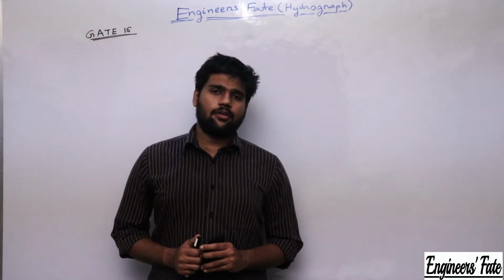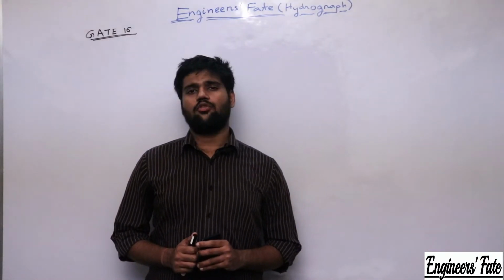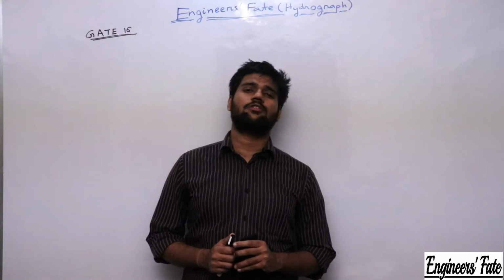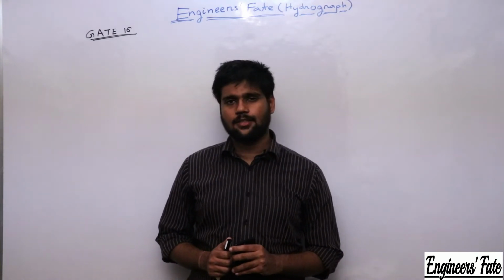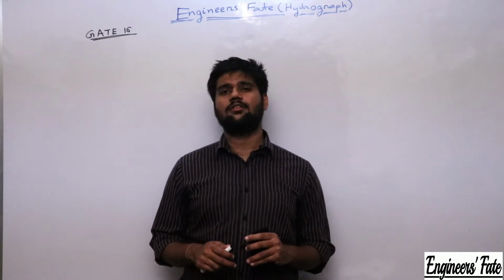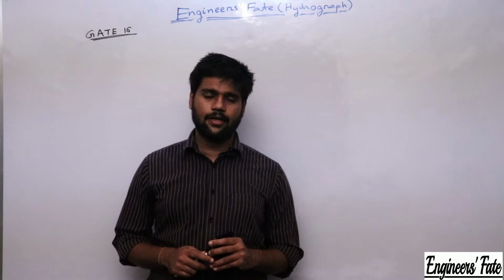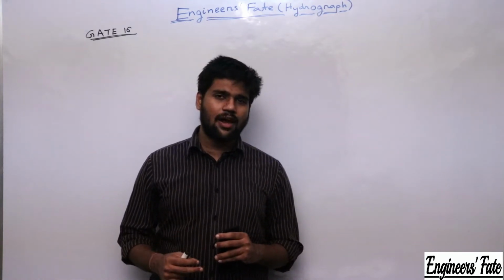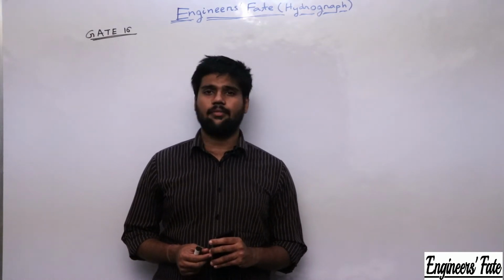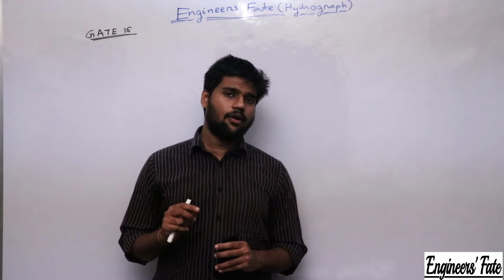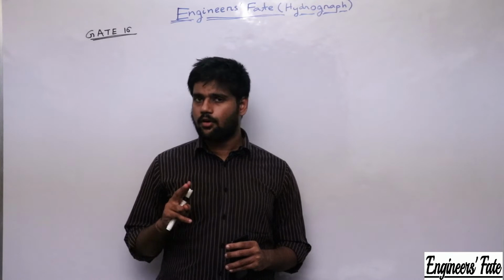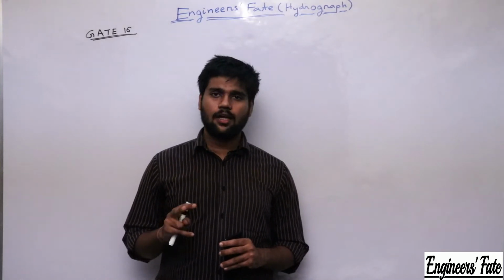At the start of the video, I told you how to find a unit hydrograph ordinate from a flood hydrograph ordinate, and I told you that if a flood hydrograph ordinate is being asked, then the process will simply be reversed and I can find that. In this question he has asked us the flood hydrograph ordinate, but before that I have to find the 2-hour unit hydrograph ordinate from the S-curve method. He has given the 1-hour unit hydrograph ordinates. I can find the 2-hour unit hydrograph ordinates, and I am going to use the S-curve method.